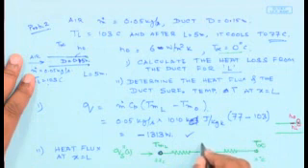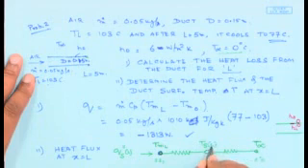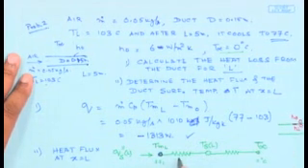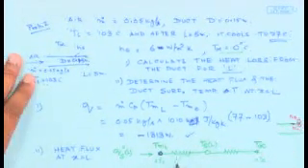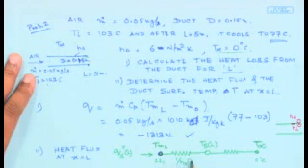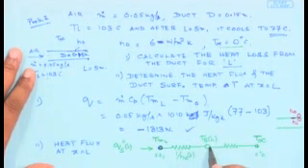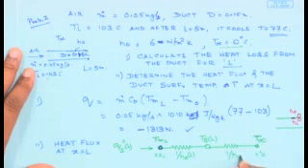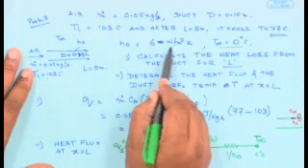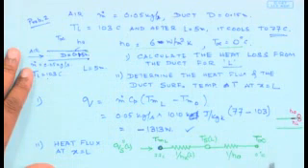This is my temperature of the surface of the duct at location L, and from inside to the wall, this resistance is going to be 1 by Hx, which we understand is a function of L, and from the outside of the tube to the outside atmosphere, the resistance is simply 1 by Ho, and we know the value of Ho, which has already been provided as 6 watt per meter square Kelvin.